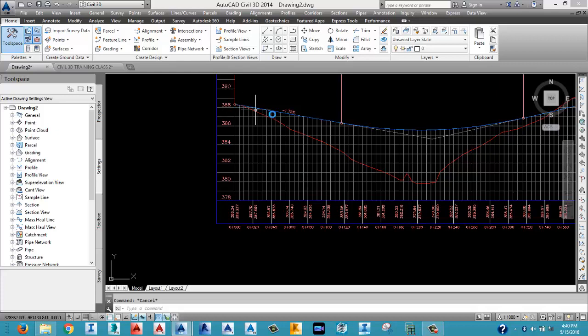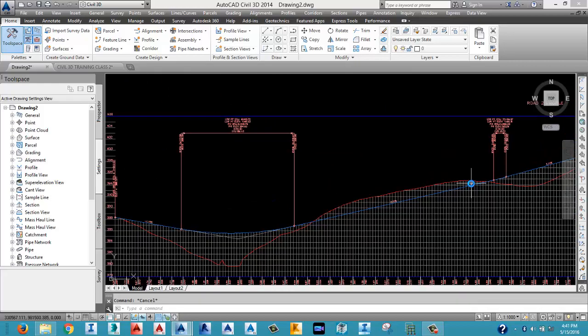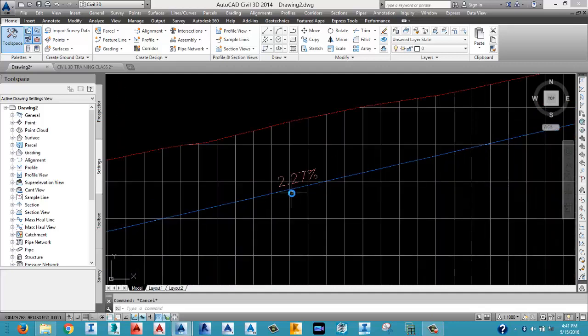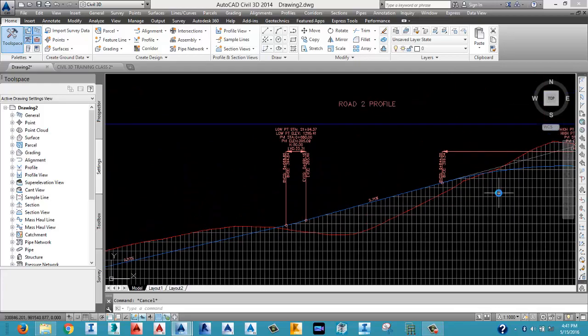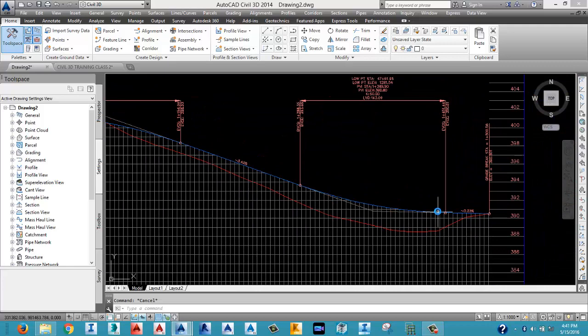But if I'm coming down in a space of 40 meters or so like that, with this particular grade, it's going to be a very steep grade. So we always think about going not less than, let's say, 100 meters. You drop, then you think about the next best point to actually drop. So just don't drop at close intervals. Whenever you are designing, you don't drop at close intervals, as well as taking into consideration your slope, grades, and so on like that. So that's how we actually design, not that we just drop.